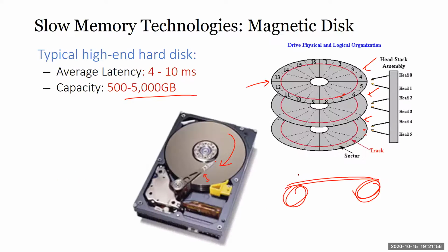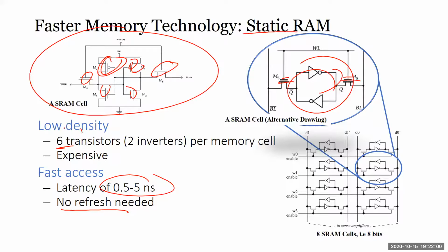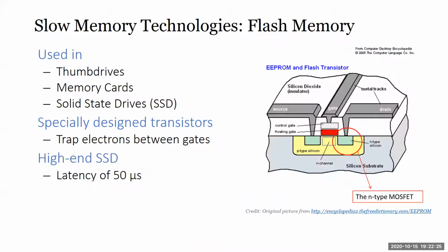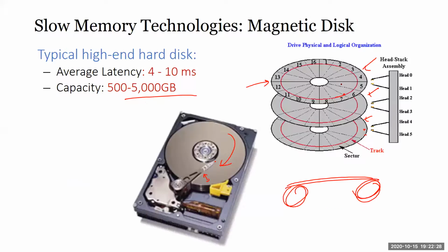Someone asked why SRAM has no refresh. It's because it has more transistors. It uses 6 transistors, so the transistors, in a way, refresh themselves, compared to SDRAM. SDRAM has only one capacitor and one transistor. So that's the design of the components. Of course, the trade-off is cost. Use more transistors, it costs more. So yes, we can easily build static RAM as large as SDRAM, but of course the cost will be quite high. So it's more of an economical sense.